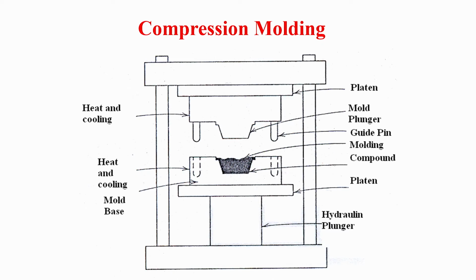Now, coming back to the different polymer processing techniques, for example, here I am showing you compression molding. Compression molding is used very widely in the polymer industry. It is a fairly simple technique. The heart of the compression molding technique is how you design the mold, because the design of the mold is dictated by what the final shape and size of the polymeric product would be.